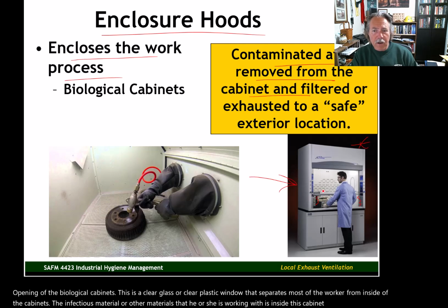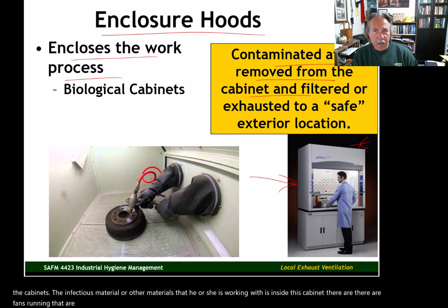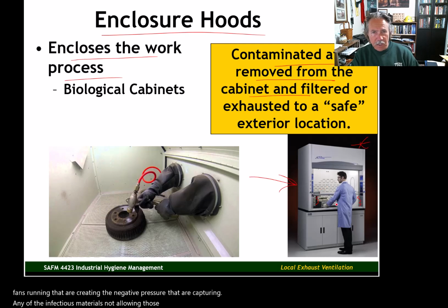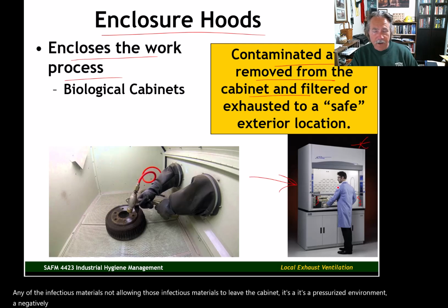There are fans running that are creating the negative pressure that captures any of the infectious materials, not allowing those infectious materials to leave the cabinet. It's a negatively pressurized environment that's not allowing material to leave that cabinet. It's really a cool design.